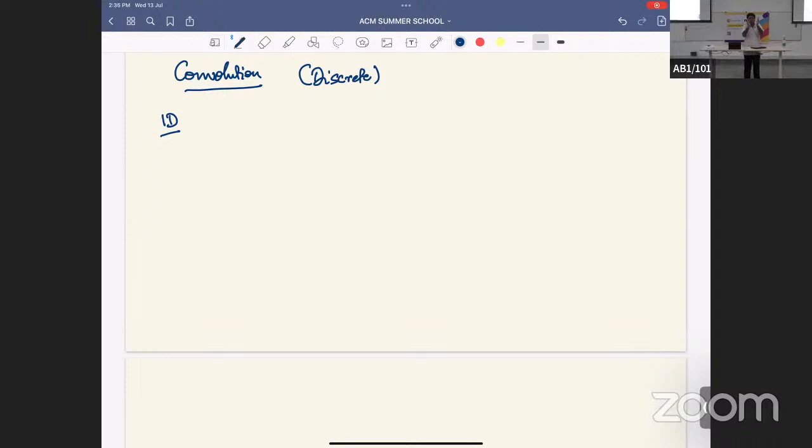That's the conventional convolution. But in image processing and also in the deep learning sense, what we are going to do is an operation called correlation and call it convolution. Okay? So we are never going to flip it. That is the first rule you need to understand, right? You will just move one across the other.